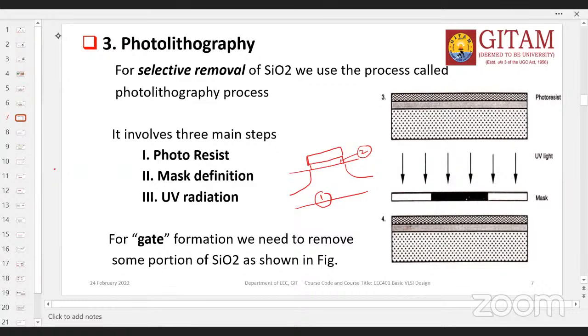Okay, but unfortunately, when you perform some kind of operations, maybe the process of forming the silicon dioxide, immobile charge carriers will be there in the silicon dioxide. Immobile charge carriers are there in that process. So that can disturb the operation of the MOS transistor. Okay, so one important fact.